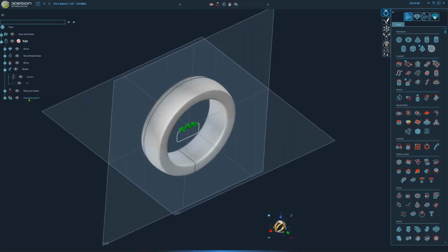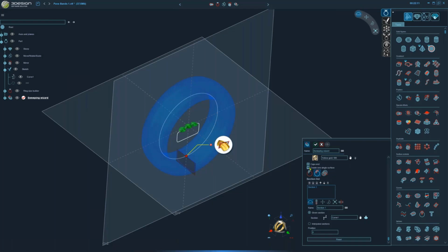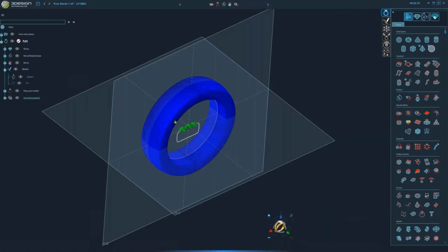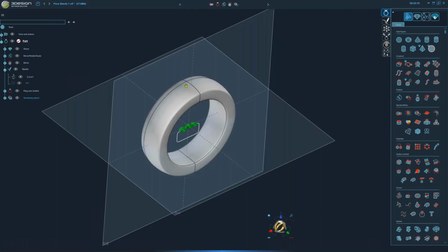And let me go back in my sweep here real quick. I have a feature turned on I want to turn off. By default, this create single surface option is usually off. So if we take a look at the topology now, we have our start point where it's splitting it there, but we also have a split on the opposite corner. And that's because by default, it's splitting all surfaces in two. That used to be the only way to do it. Eventually, as Booleans got stronger and our tools got better, they decided to put this feature in where you can force it to do single surfaces. Used to be that it just always split them in half.